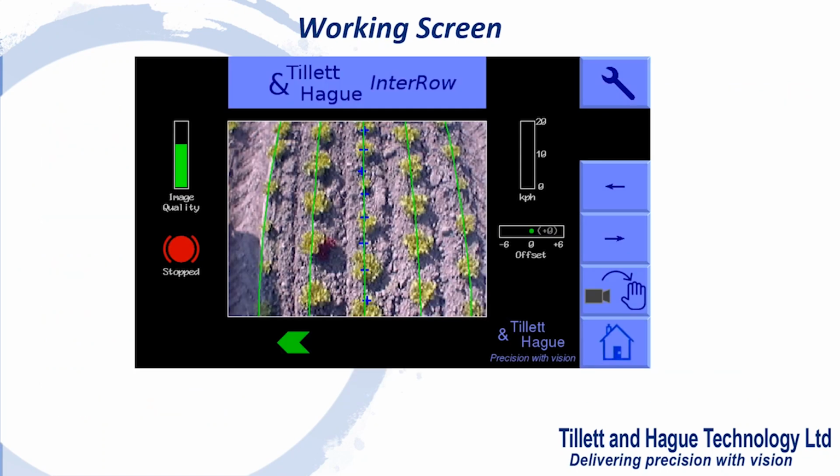This is the working screen. It features a live image with template and tracking crosses overlaid. A green dot or green chevrons below the image indicate side shift or disc steer position. A red chevron with a vertical bar indicates the limit of travel has been reached. This should not be allowed to occur for extended periods.